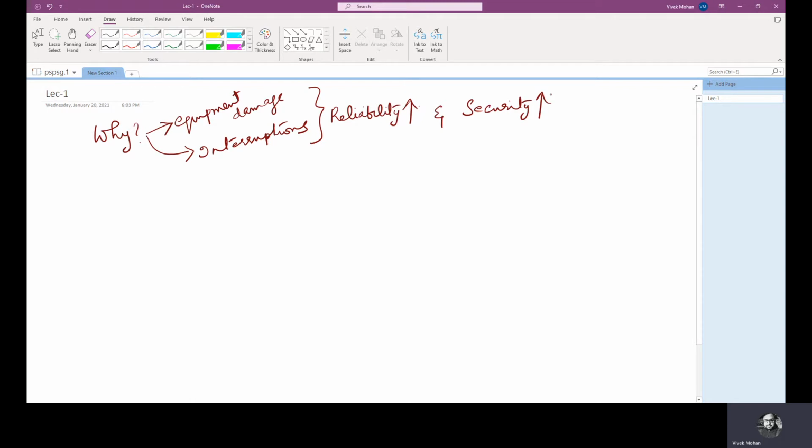That will cause a rise in temperature, which may fail the surrounding insulators also, which leads to spreading of the damage or spreading of the fault. So the fault current increases and later it may lead to melting of conductors and damage of the steel laminations itself.